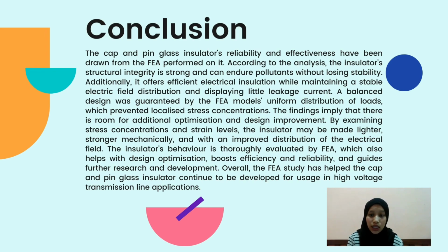The findings imply that there is room for additional optimization and design improvement. By examining stress concentration and strain levels, the insulator may be made lighter, stronger mechanically, and with an improved distribution of the electrical field. The insulator's behavior is thoroughly evaluated by FEA, which also helps with design optimization, boosts efficiency and reliability, and guides further research and development. Overall, the FEA study has helped the cap and pin glass insulator continue to be developed for usage in high voltage transmission line applications.